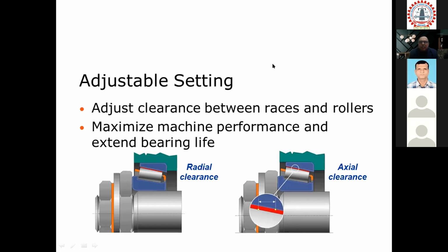Nowadays, there are new technologies which have come up, which is called condition monitoring. They pick up the signal from the shaft and housing, and then those signals are recorded on a regular basis. So basically, if a bearing is rotating, there will be a different frequency coming for the roller and race, right? Yeah. Race may be 1 RPM and roller may be 20 times of that. So the signal will tell where the frequency is changing. Similarly, it will also know that in the system, if there is a gearbox, how many gear teeth are there.